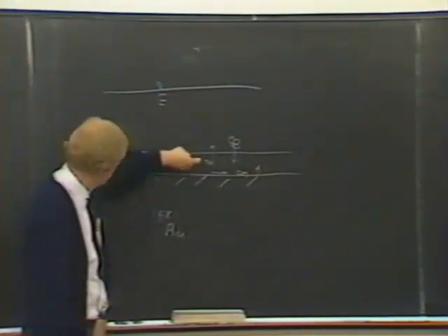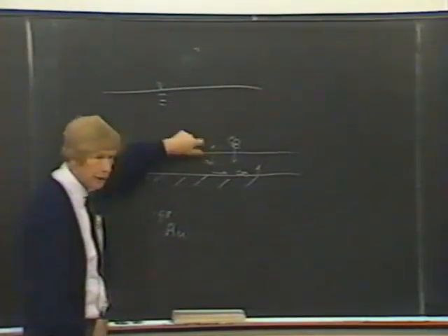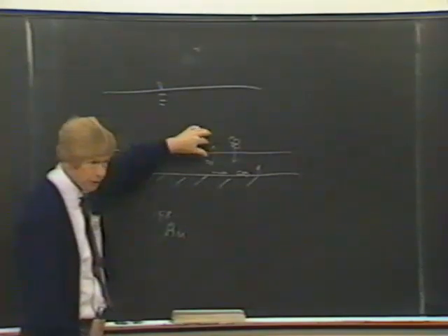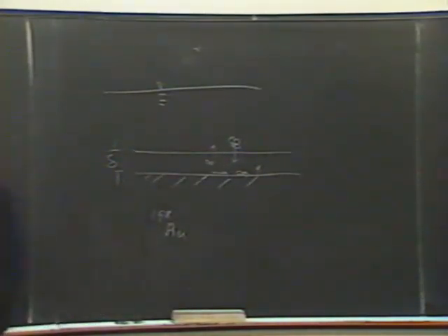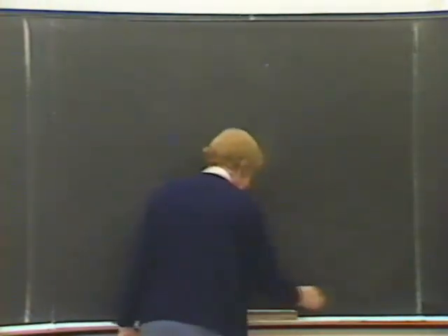Now let me tell you why the skeleton, or the matrix, crushes the particles at lower elevation. So if we have a bed that's formed of aggregates settling on one another, the aggregates at increasing depth experience the pressure of the weight of the particles above them, so that at some point they'll begin to collapse. And of course, when they collapse, that means more contacts per particle, which means that the bed is stronger. So you'd expect it to become stronger with depth.